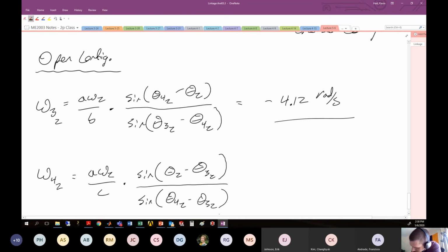All right, looks like I might have a question here. Sorry if that question's been sitting for a bit. What would happen if theta 3 and 4 values were imaginary? Okay, thank you for the question, Peter. If they were imaginary, that would tell you that the linkage could not be configured with the links given. That could be possible, as there are many configurations where that might be impossible.